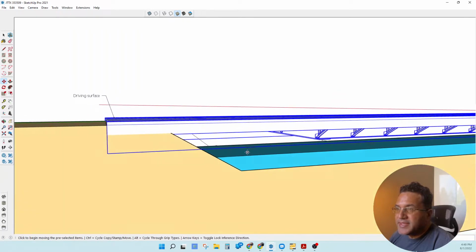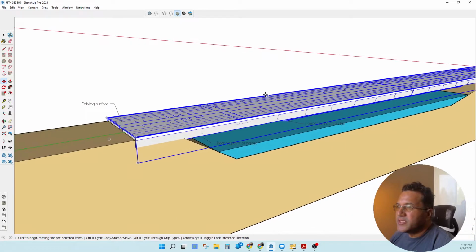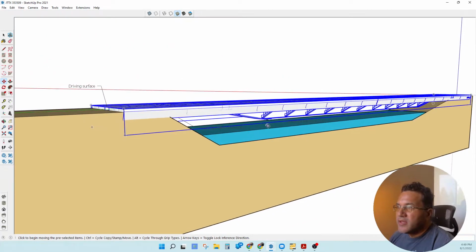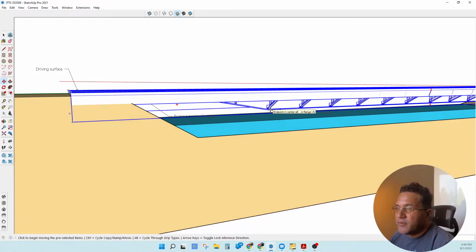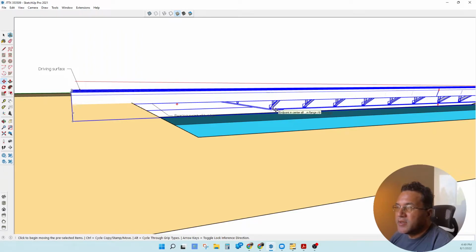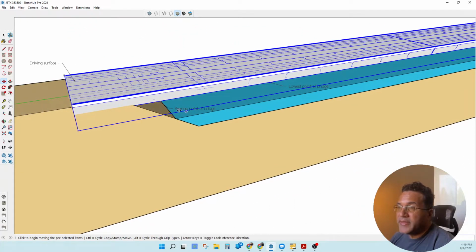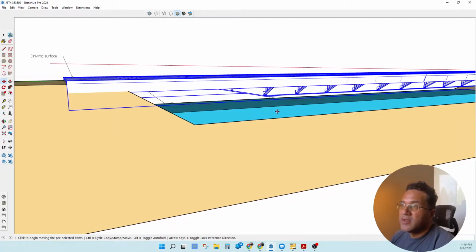the problem with this is that oftentimes the government jurisdiction that's controlling this waterway, when we're getting a permit, you can see that there's another term we need to talk about. It's called freeboard. Freeboard is the amount of space between the bottommost part of the bridge and the bottom of the waterway. Sometimes they measure freeboard from the bottom of the bridge, the lowest part of the bridge, and the top of the waterway. That's the amount of freeboard space you have underneath the bridge.